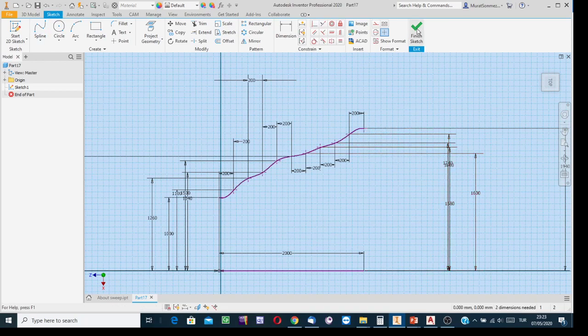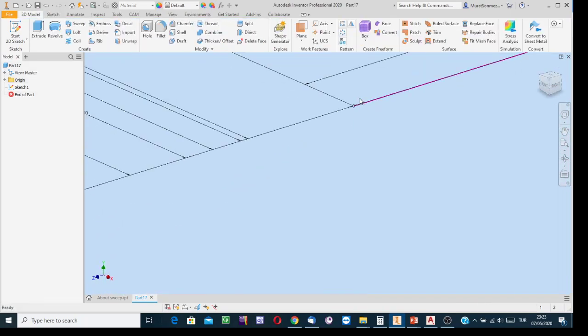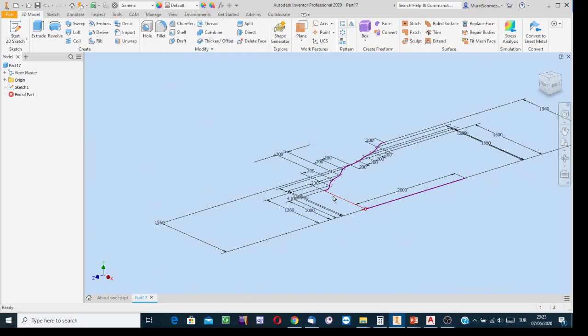Yes. Finish the sketching stage, and then, well, the profile at the beginning of the loft, it is my consideration these 2 points, the starting point of this path and this guide, are in the same plane, and in the same plane, have the profile of the loft at its inlet.